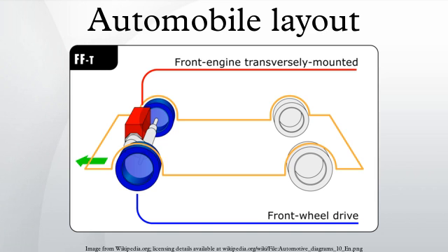Increased weight. The components of a rear-wheel drive vehicle's powertrain are less complex, but they are larger. The drive shaft adds weight. There is extra sheet metal to form the transmission tunnel. There is a rear axle or rear half shafts, which are typically longer than those in a front-wheel drive car. A rear-wheel drive car will weigh slightly more than a comparable front-wheel drive car.